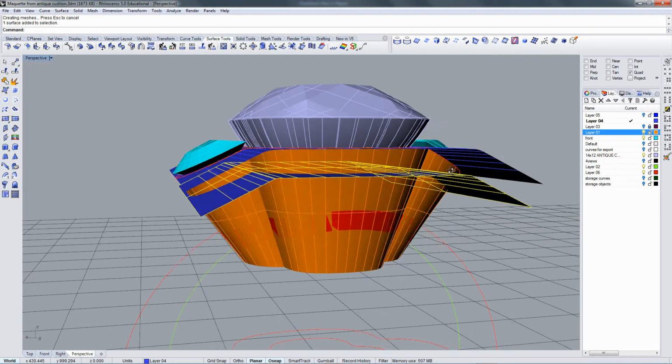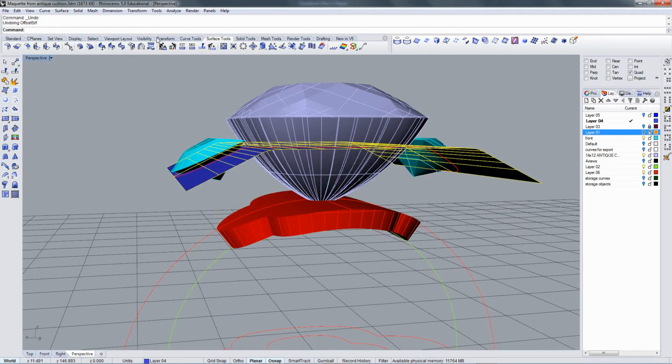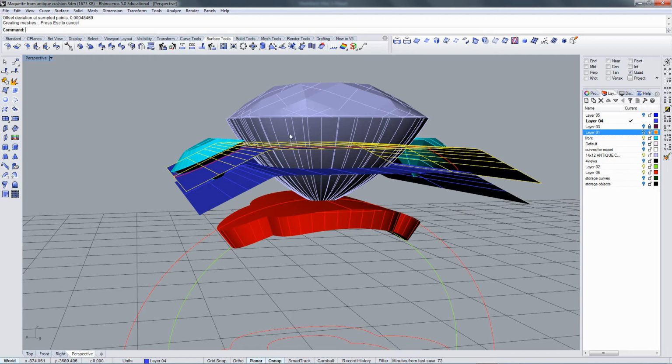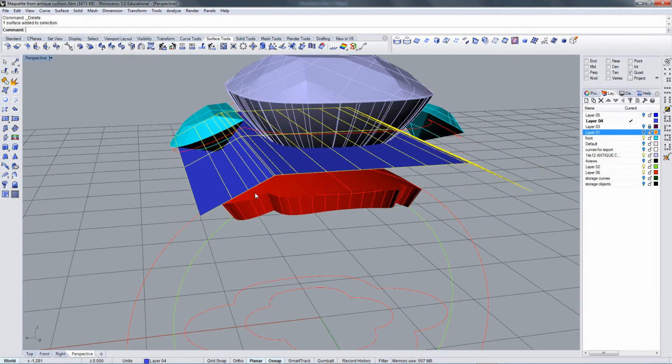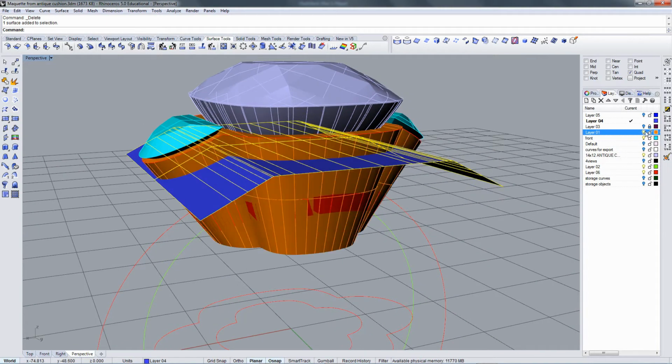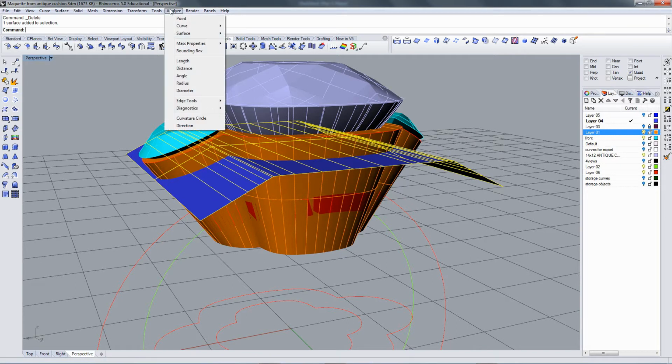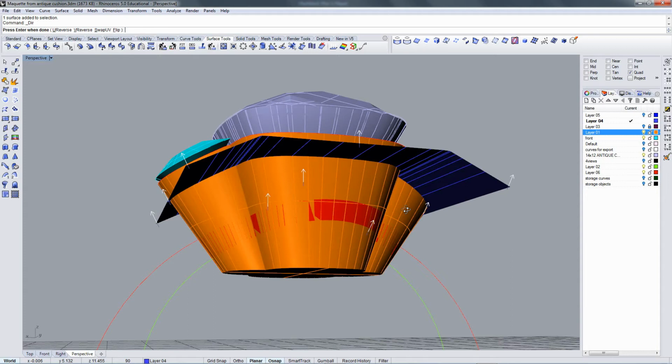I'm going to take a look quick, because at the end of the day, I think that's heavy. I'm going to offset at 1.1, -1.1. I like that better. I have no use for that surface, going to throw it away. I'm going to Boolean this with this surface, but I want to keep the top piece. So I want to make sure that the direction of my Boolean cutter points towards what I want to keep. So analyze direction. And it is pointing towards what I want to keep.